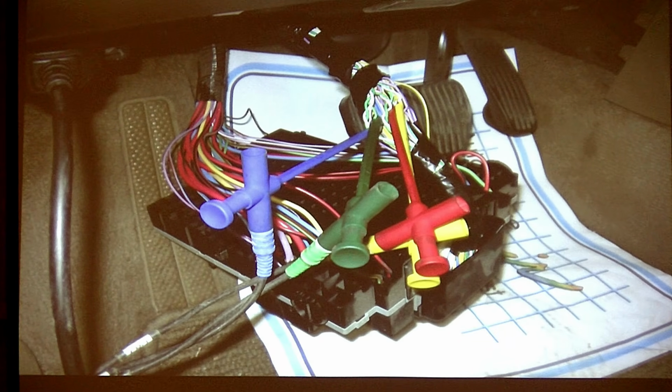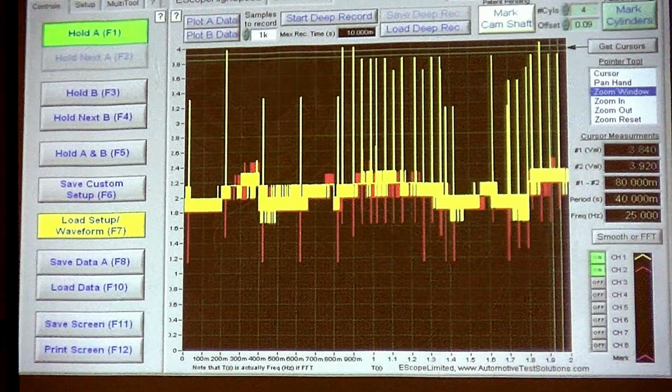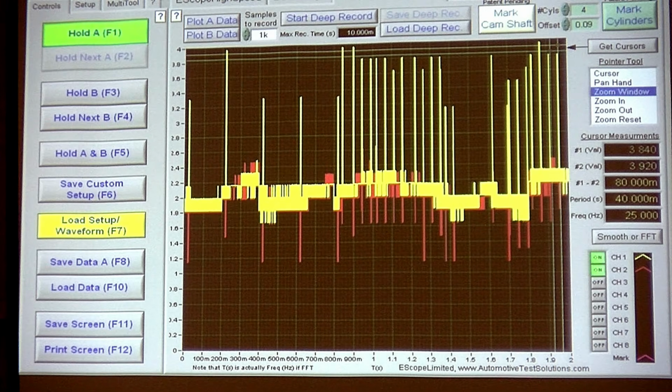Some of these cars, you've got to transmit the information from your security system from a low-speed bus to the high-speed bus or it's not going to start. And you can have problems with the bridge not bridging that, and that's why it's not starting. So I want to make a point here. Basically, I want low and high speed. I want to see who's coming up and who's not coming up. So now I've got this. Is that any kind of a waveform?